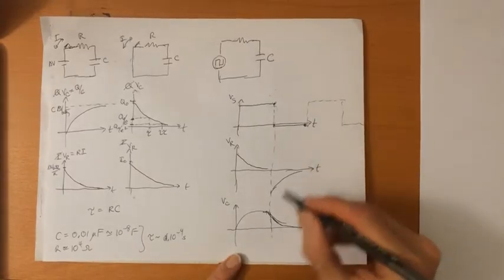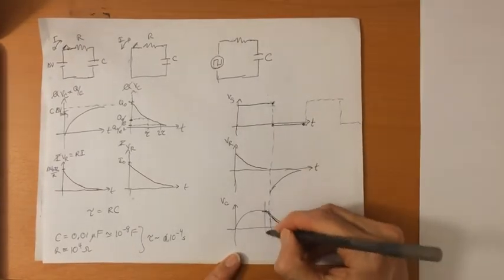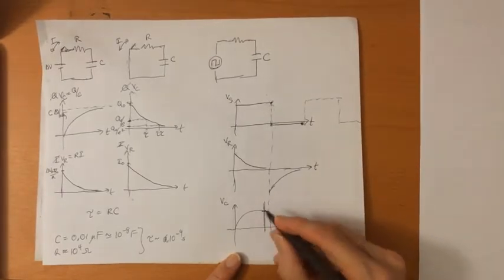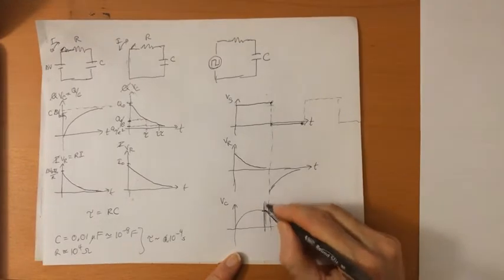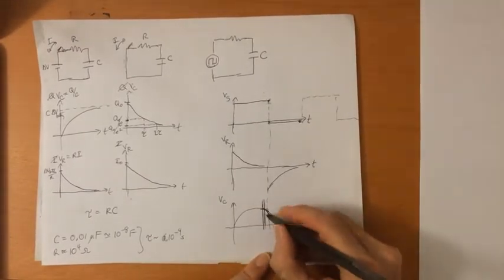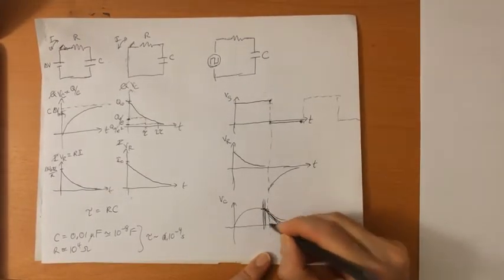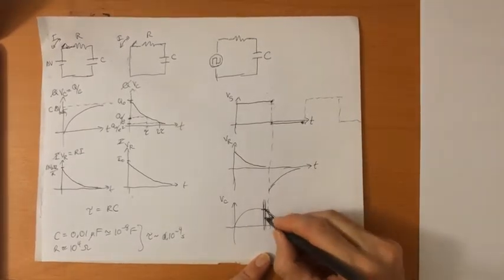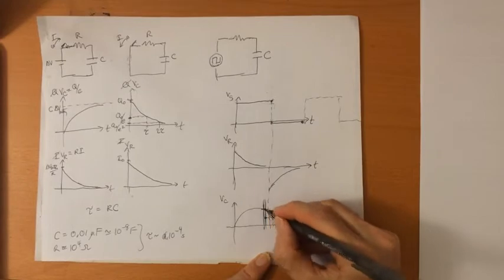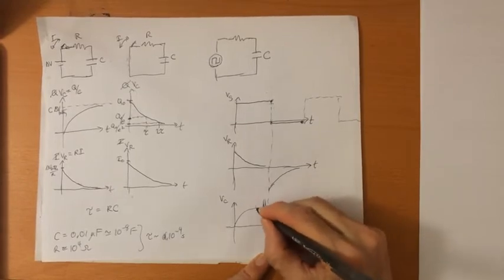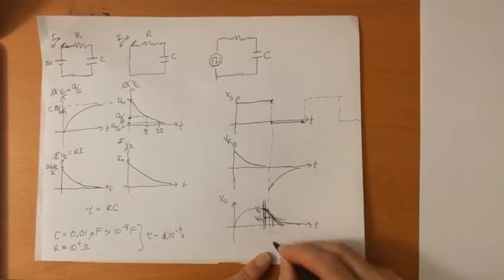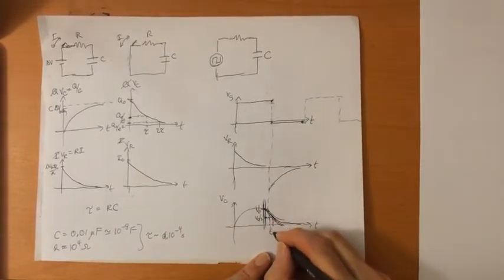And so one of the exercises I'm going to have you do is, let me actually, this is the start here for the decay curve for the capacitor. I'm going to have you take these curves and demonstrate what is called the half-life property. So this is kind of a starting voltage here. So think of this as V0, and then this will be V0 over 2, and there's a certain amount of time, which is the half-life.